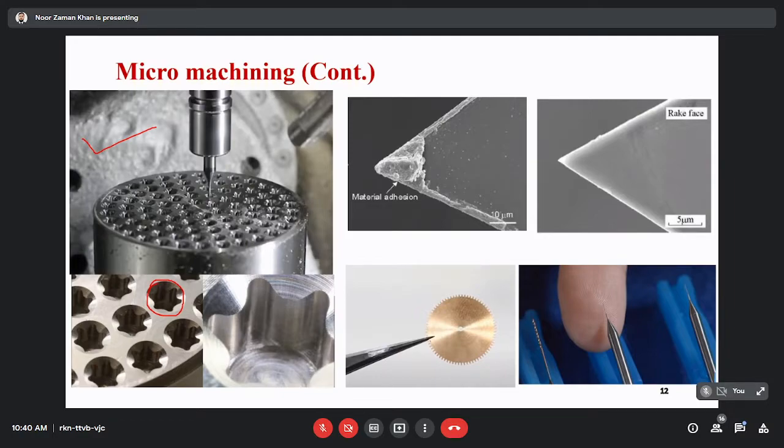of holes, and then in these holes, a micro end mill was used to produce a micro scale profile on the pattern of holes. This micro scale profile. Because this hole is around 3 mm, we cannot produce the star like profile by using a 3 mm end mill. We require a micron size end mill for producing this profile on the area of these holes.